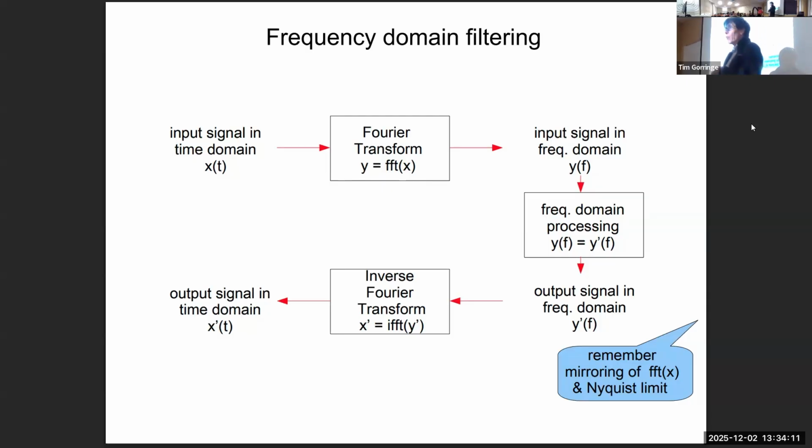If we want to say, well, why don't we just take our time domain signal and convert it into a frequency domain signal and work there, we have to have the whole time domain signal to convert into a frequency spectrum. And so in some applications, where you're using digital filtering in real time, this is not applicable. In other applications, you have your time spectrum and you can turn it into a frequency domain spectrum.